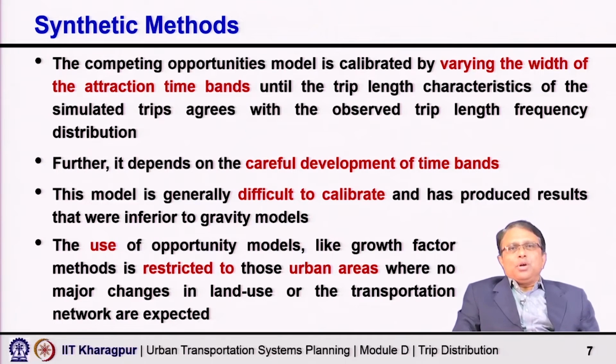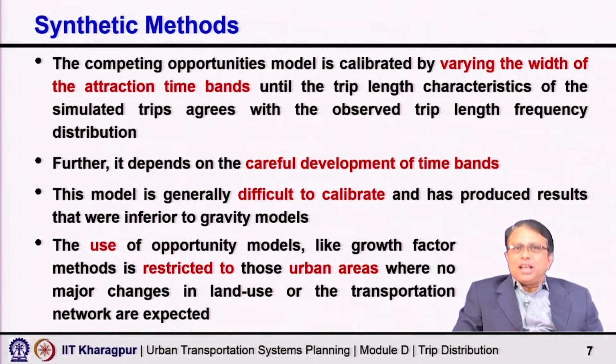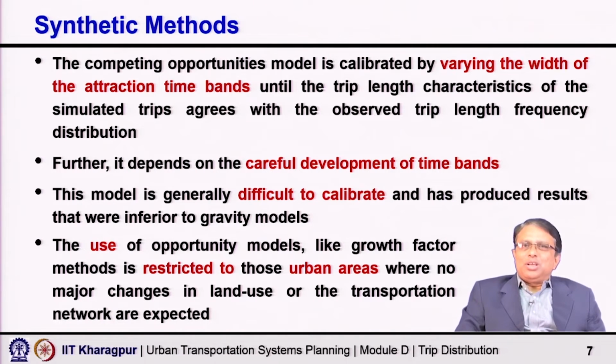The use of opportunity models like growth factor methods is restricted in urban areas. We know that the use of growth factor models is restricted; only in certain cases do we use them, otherwise, wherever it is possible and feasible, we prefer to go for synthetic models.